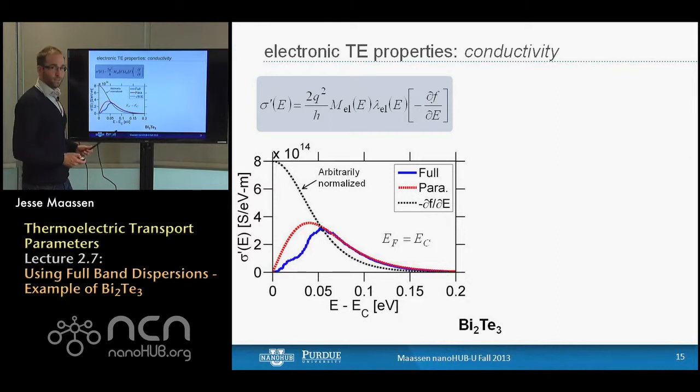There's some discrepancies here. So initially what we see is that the differential conductivity increases initially because the modes are increasing, but eventually drops down because of this Fermi window function, the occupation function, which is shown as a black curve here. That essentially suppresses everything. So that when you look at this, with the Fermi level located at the conduction band edge, most of the conduction, the average conduction, is always a few kT inwards in the conduction band, as you can see here.